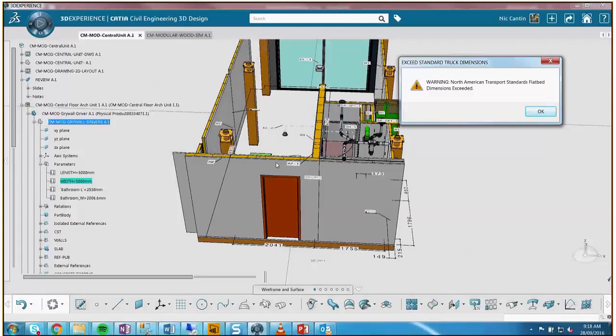The way we would handle that, though, is as you can see here, the columns didn't move. It's its own assembly. So say we were given through FEA or whatever from the structural engineer, here's where the locations of the columns need to be. Let's try to find the most optimized way to make it modular. We could have that as its own assembly within the master assembly that could be updated separately if needed. So, you know, maybe some modules have columns in the middle of it potentially, right?